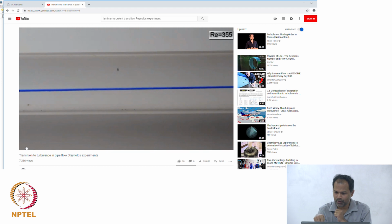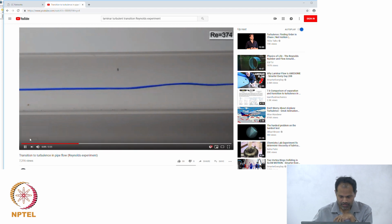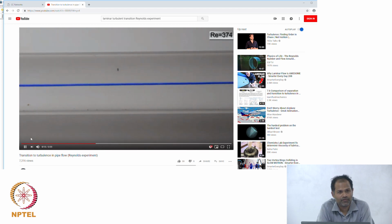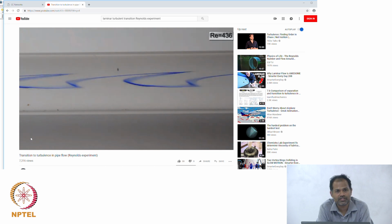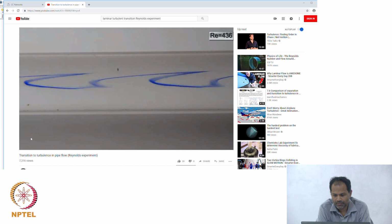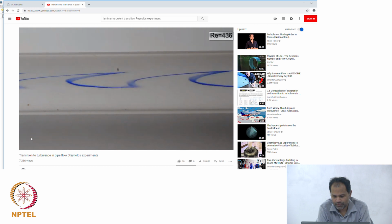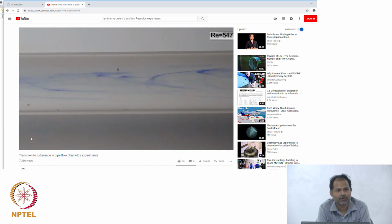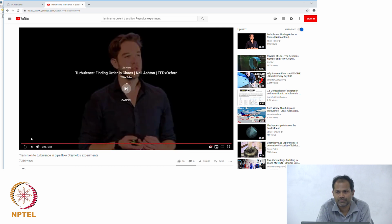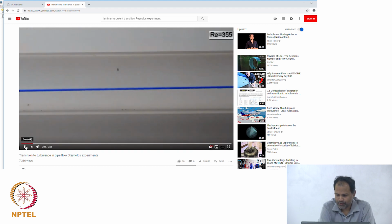So on the right hand corner, you can see the Reynolds number. The Reynolds number is 355. Now they are hiking up the Reynolds number, so the flow becomes sort of unstable, but it's still smooth. Now this is basically the transition, where you start seeing some bursts. The flow rate is increasing, and you can clearly see that now the bursts become completely dispersed. So that's basically the turbulence. I'll just play that again.